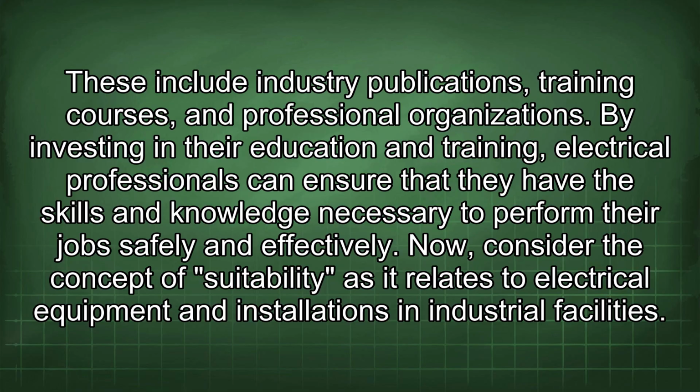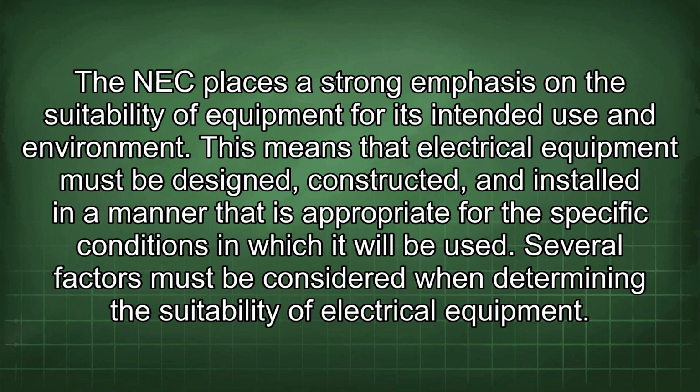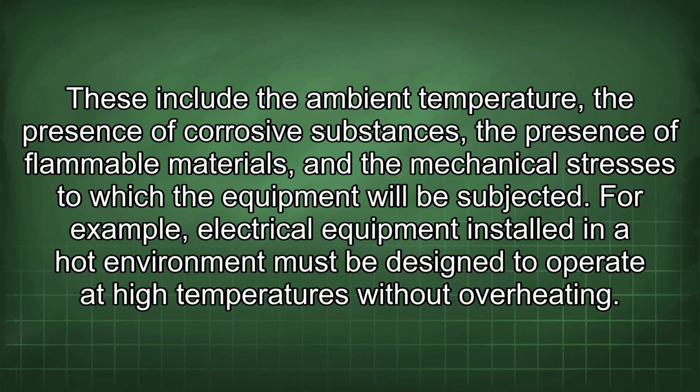Now, consider the concept of suitability as it relates to electrical equipment and installations in industrial facilities. The NEC places a strong emphasis on the suitability of equipment for its intended use and environment. This means that electrical equipment must be designed, constructed, and installed in a manner that is appropriate for the specific conditions in which it will be used. Several factors must be considered when determining the suitability of electrical equipment. These include the ambient temperature, the presence of corrosive substances, the presence of flammable materials, and the mechanical stresses to which the equipment will be subjected.